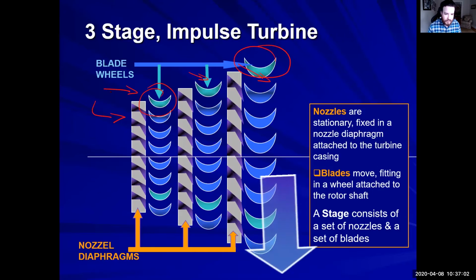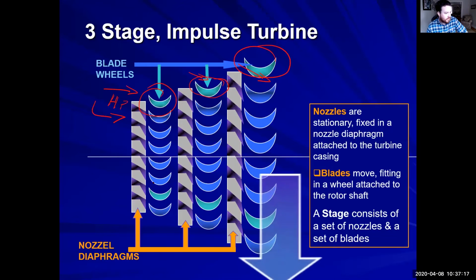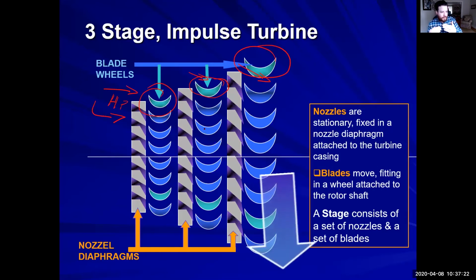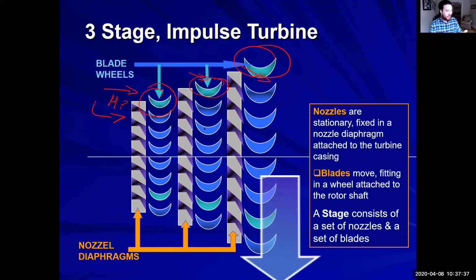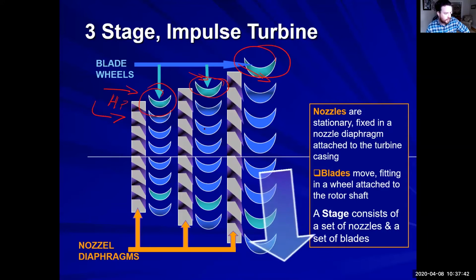But what's happening is we have a higher pressure here, then on the other side of that we have a little bit less pressure, but we increase our blade. What we gain is more force being applied to a larger blade. So it allows us to exert the same amount of force, even though we have less force to give with the same amount of volume of steam.